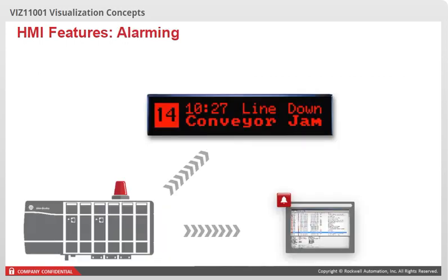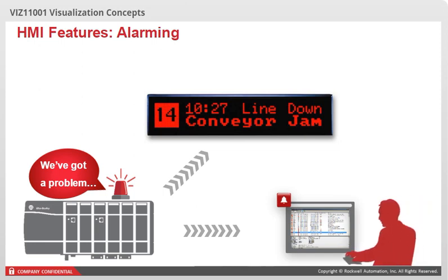Next, let's address alarms. By definition, an alarm is a visual and/or audible signal indicating an occurrence of an abnormal condition that requires an operator action. Alarms are displayed in the HMI on a graphic referred to as an alarm summary display. Within this summary, operators can interact with the alarms to validate and initiate remediation as necessary. ISA 18.2 standards define types and guidelines for alarm interactions, such as acknowledging, suppressing, silencing, and shelving, just to name a few.